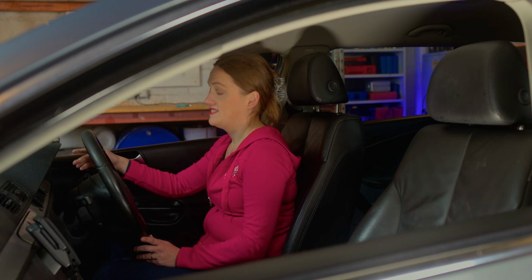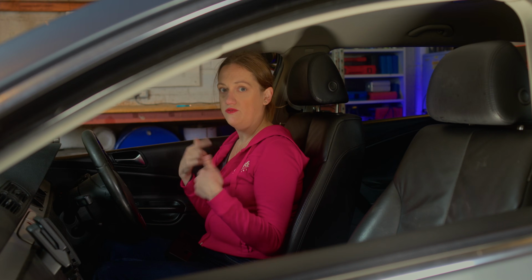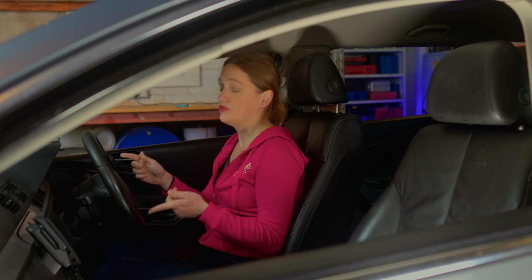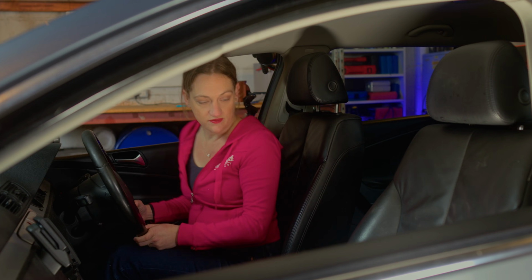The tyre pressure system on here works through the ABS. What it does is it calculates the wheel speed of all the tyres, and if it finds one tyre that's different from the other three, it decides that it must be deflated. The traction control also works through the ABS to stop the wheel from spinning, so as soon as you get an ABS fault, you get all three of these lights on. Let's get the diagnostics out and see what fault codes we've got.